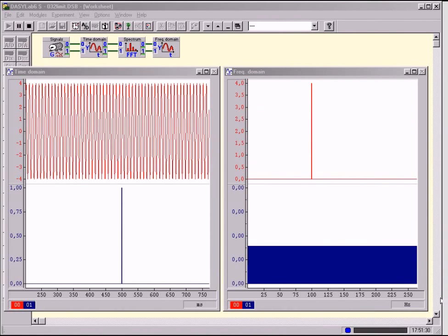Sinusoidal signal and delta pulse as a limiting case of the uncertainty principle. A delta pulse in one of the two domains, that means delta t against 0 or delta f against 0, always implies an infinite extension in the complementary domain, delta f against infinity or delta t against infinity. This illustration shows a sinusoidal signal, which means delta t against infinity. This implies delta f against 0.